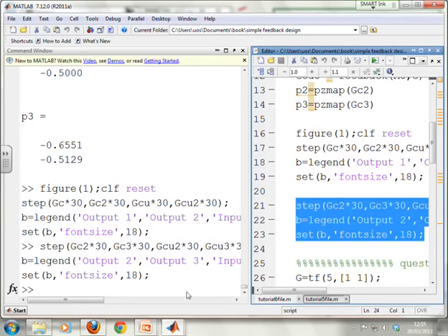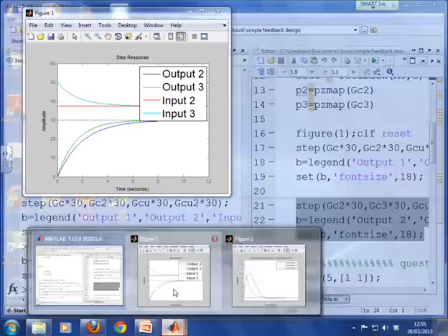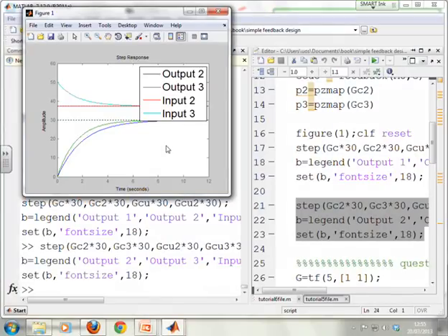So there, we've done the response. We'll just go to the window. So this one is looking at M2 and M3. So the heuristic is now this blue one. And you'll see by increasing Kp up to 1.67 instead of 1.25, we've got a slightly faster rise time, slightly faster settling time, but we've paid for it with a slightly bigger input during transients.